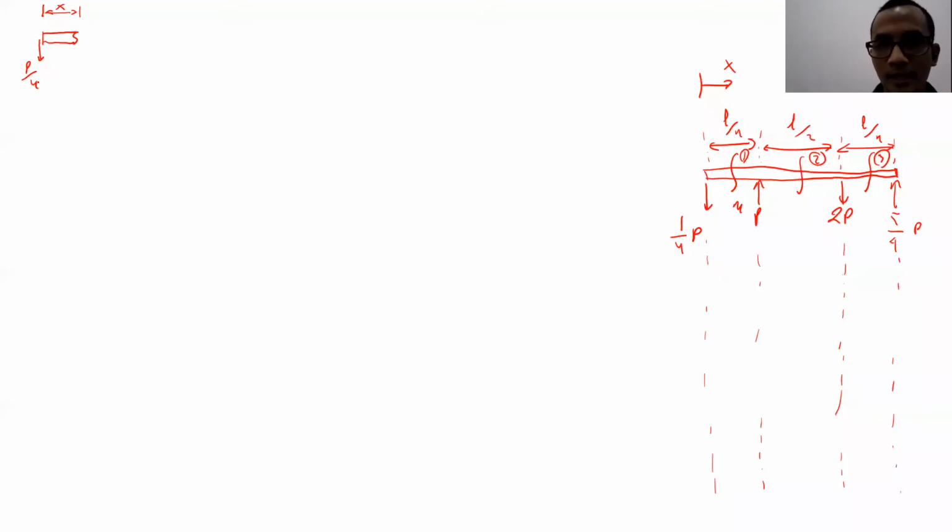And whenever we have a section, as I told you before, what things will be there in the section? Normal force, and then shear force, right? The direction of the positive shear force, remember? Going up, always use this. Okay, moment. This is the positive, remember, on the right edge. Shear force positive is going up or down? Oh, down. Sorry. Take a look at this.